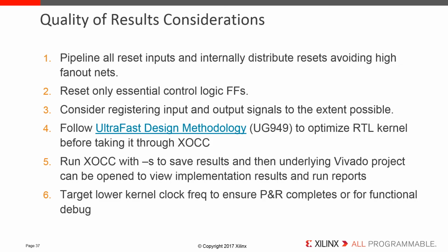Now let's look at some recommendations to help improve the timing and resource utilization for your RTL kernel. Try and pipeline the reset inputs and distribute the reset as a tree to minimize the fan-out on the reset. Only the minimal number of essential flip-flops should be reset. The data path flip-flops on the FPGA do not need to be reset as they will come up in a known state. However, the control logic should be reset to ensure a safe state. Always register the input and output signals where possible.